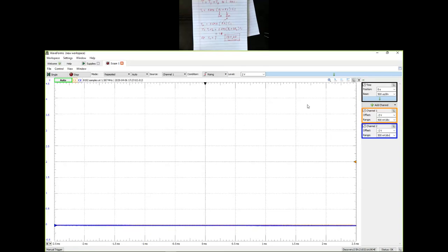And with 1 second, of course, I'll be able to see the light blink. How do I get this? Well, in my parts, I had 100 microfarad, 22 microfarad, and also 47 microfarad. So I used a 100 microfarad capacitor in parallel with a 47 microfarad capacitor to get close to 137 microfarad. Instead of 137, I used a 147 microfarad capacitor.